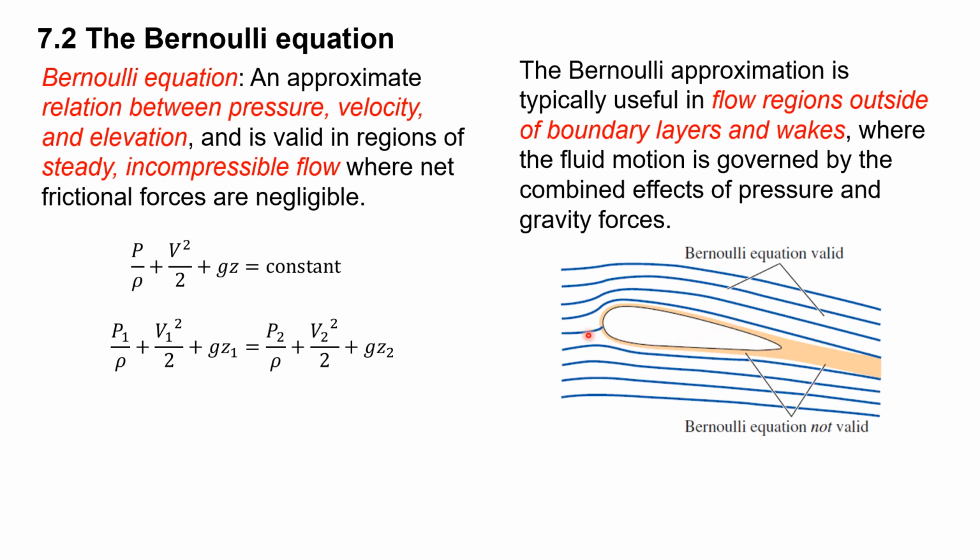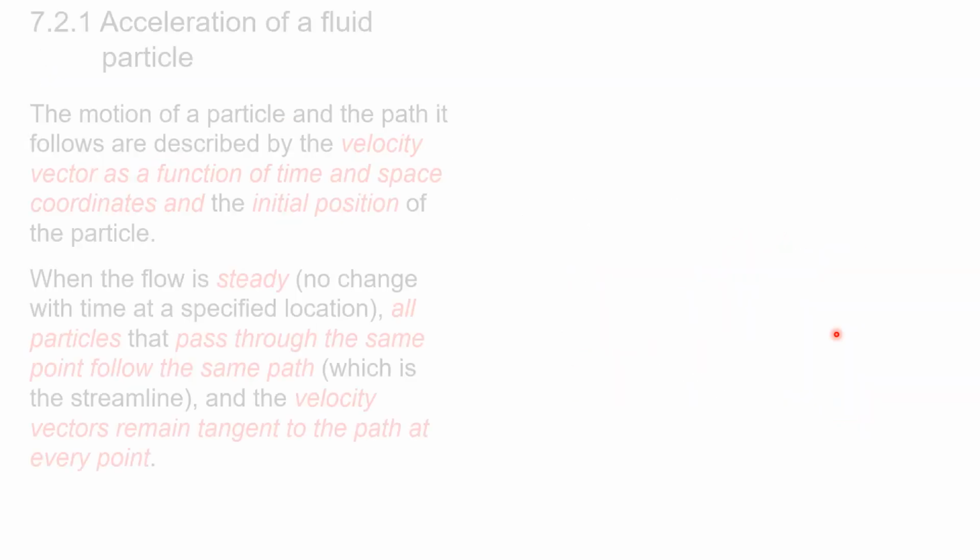After some time, suddenly this flow stops because suddenly there is friction, so Bernoulli's equation cannot be used in this region. But along this streamline, here point 1, here point 2, you can take the values and use this formula to find the unknowns. These are the regions where Bernoulli's equation will be valid. Later I will tell you what the other points are that make Bernoulli's equation valid. This is one of the points.